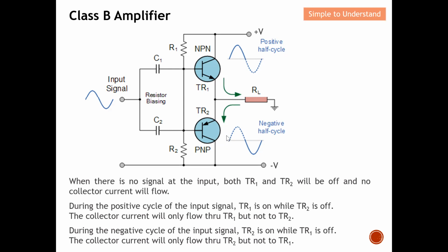I'm not sure whether you see a potential issue here. For a transistor, you need to have a 0.7 volt bias to turn it on. Anything less than 0.7, the transistor will not be on, and this becomes a potential issue which we need to address in this video.